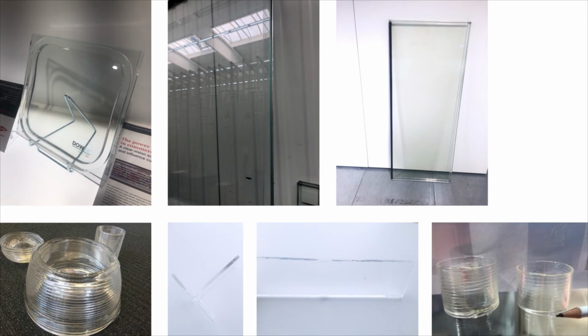And what's clear to us is that we're really at the limits of what's possible in terms of glass panel sizes. We're up to 20-meter panels by 3.2 meters. Whether it goes significantly larger than that, we don't know. But what our studies show is that what needs a lot of work, and what we would like to pose as a question or a desire to everyone here in the industry, is going towards transparent connections. So actually joining the panels together in a durable and transparent fashion is something that we think needs a lot more attention.